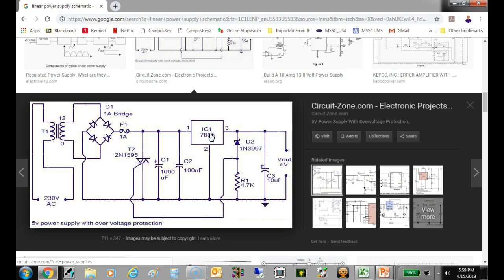It's like your car. Your car's got the same thing in there. It's got a regulator. If the output of your alternator tries to go down, the regulator makes it stay up. So you can turn your lights on, run your air conditioner, do everything. And if you measured the output of your alternator, it's going to stay around 14 volts no matter how many loads you're running. It will drop down a little bit because there's no such thing as a perfect regulator. So the transformer sets the voltage on output.